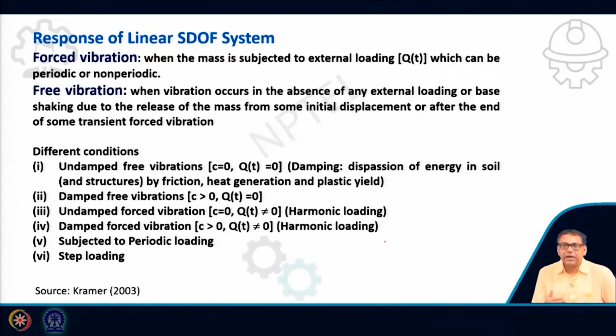From there you will get an idea of how that maximum response can be calculated, and then finally the response spectra can be obtained. So now, what is the response of a linear single degree of freedom system? First we can say what is forced vibration and free vibration. Forced vibration means the mass is subjected to external loading, which can be periodic or non-periodic.